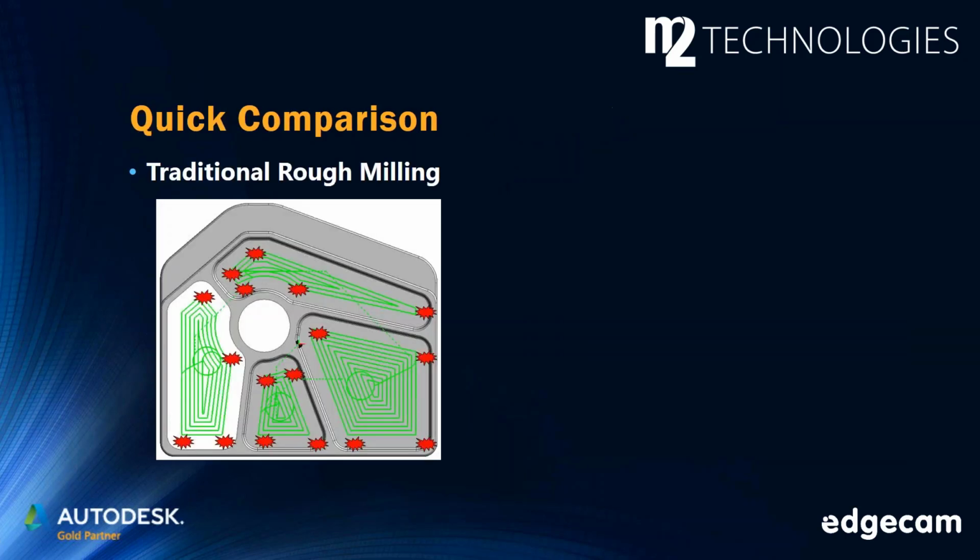Let's do a quick comparison. We have a screen image of a typical prismatic part, so some simple pockets, and the green path that you see is where the center of the tool is going to operate. So that's the center tool path. You can imagine how this will sound at the machine. As the tool moves into the corner areas, we've put some red flags or stars on the areas where the tool load gets heavy. As the tool pushes into corners, the load is very heavy there. We would hear that out of the machine. There's also abrupt redirections in some cases for the machine moving in one direction out to another, and that's obviously not desirable at all under high-speed machining.